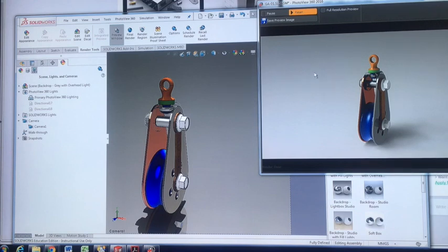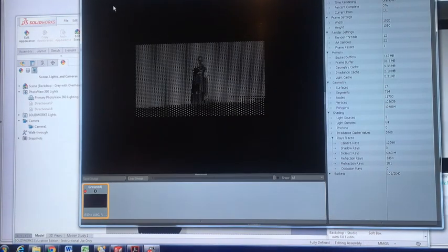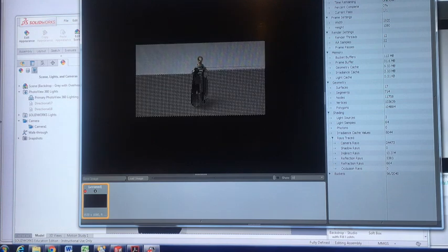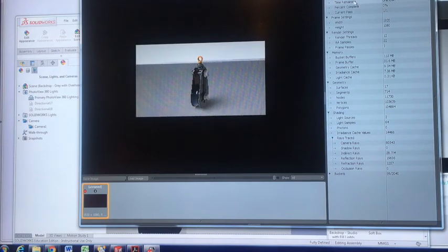At this point with the preview, you can go back and change your materials, change your lighting, whatever you need to, but when you're happy, that's when you can hit final render, and I'll go through the render process. So, how SolidWorks works, it's got this thing called a radiance pre-pass, which we'll go through. On the side, you can see render time, time remaining.